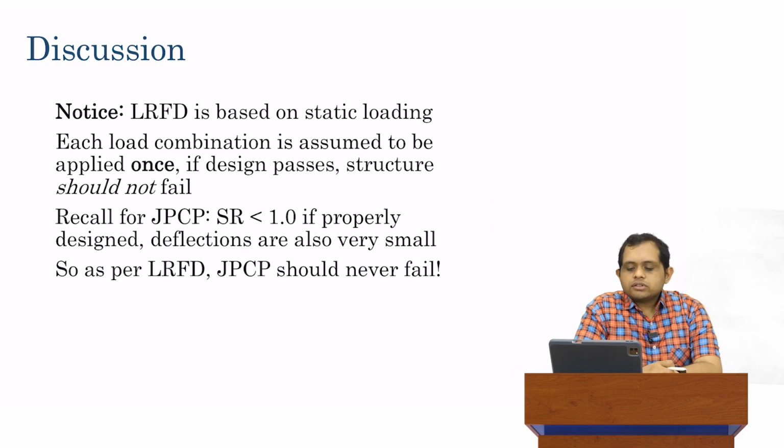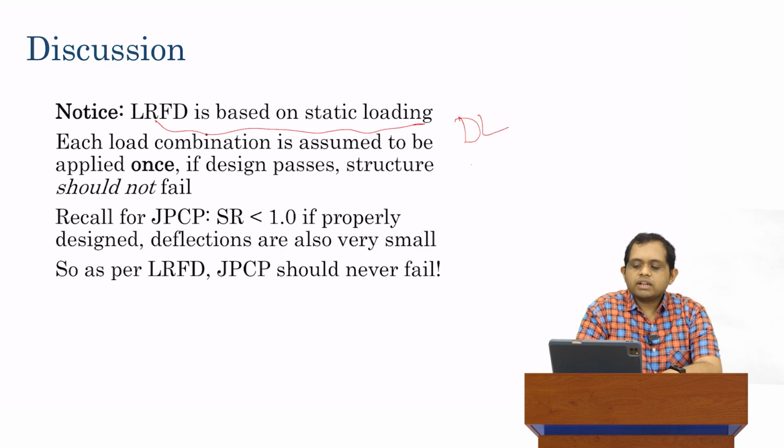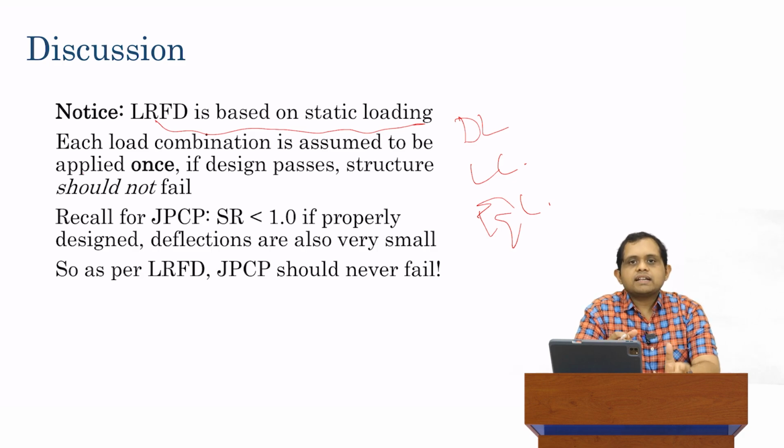Now, let's go a little bit deeper and look at some of the underlying assumptions in LRFD. LRFD is based on static loading. Note, I said that we'll have various combinations. We'll have a dead load, we'll have a live load, we might have an earthquake load, etc. And as I said, these loads are going to be multiplied by some amount of load factor in various combinations, and that's going to give us the loads that we have to consider.